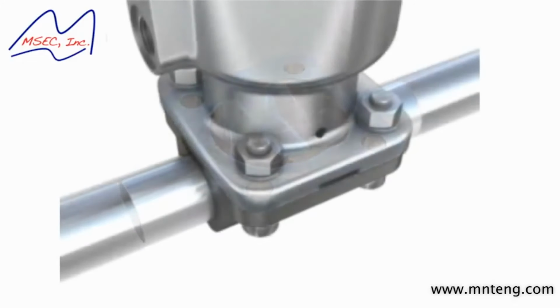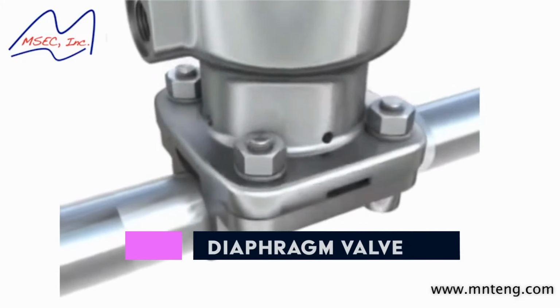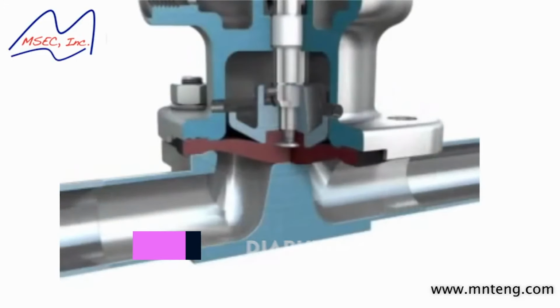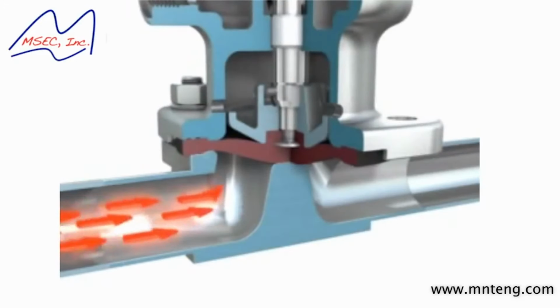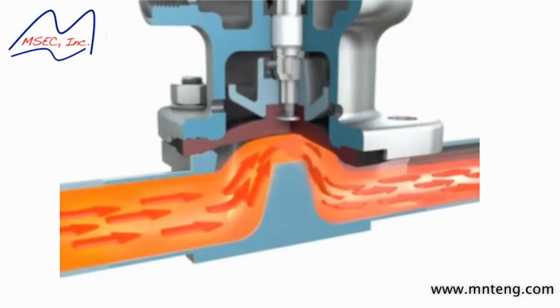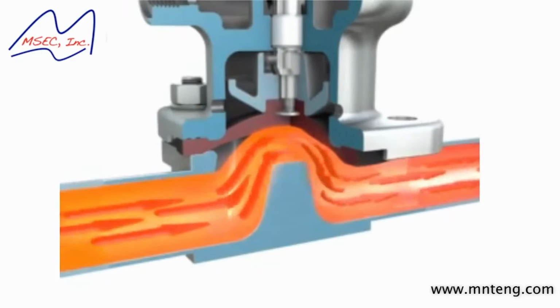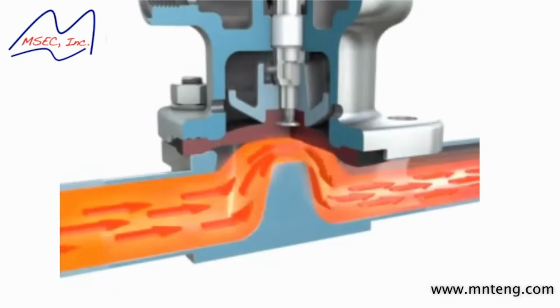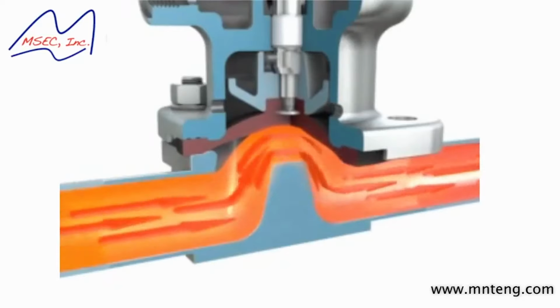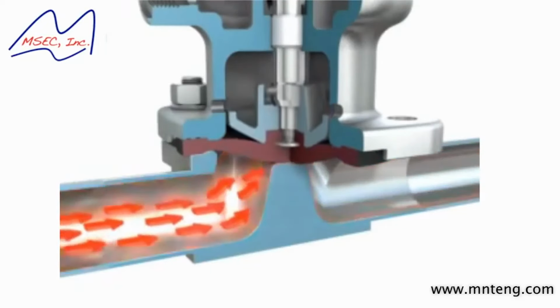Another type of actuated linear valve is the diaphragm valve. In this valve, an elastic diaphragm sits above a weir, which is essentially a little hill in the pipe. An operating mechanism pushes the diaphragm against the weir, closing the valve. The stretchy material of the diaphragm smooths hard edges that might erode away in really chemically harsh liquids, and squishing the diaphragm on the weir can create an airtight seal.